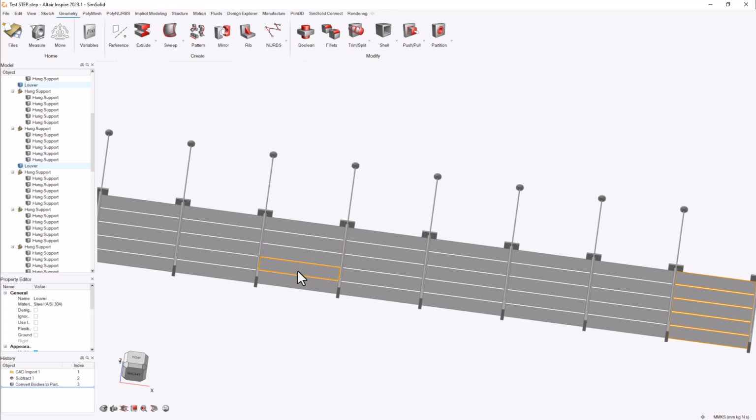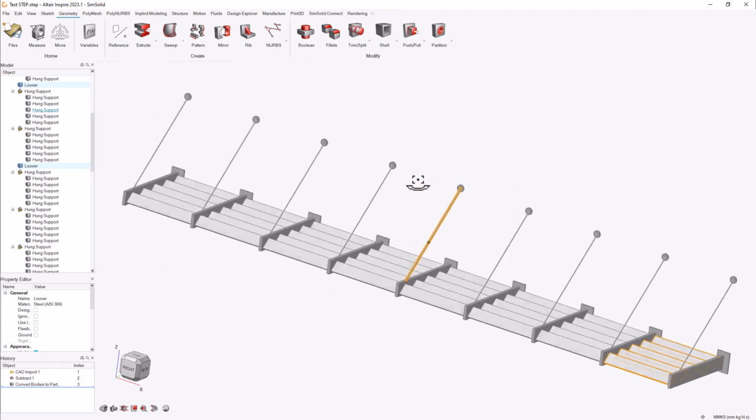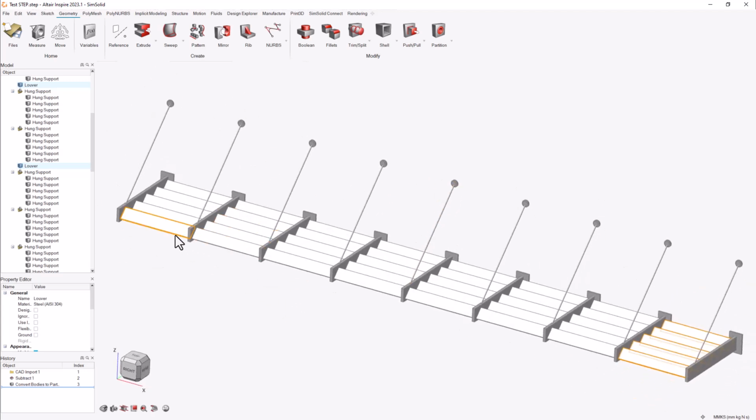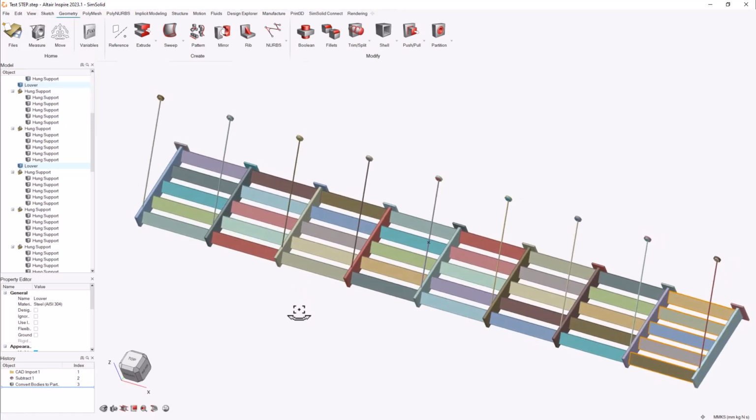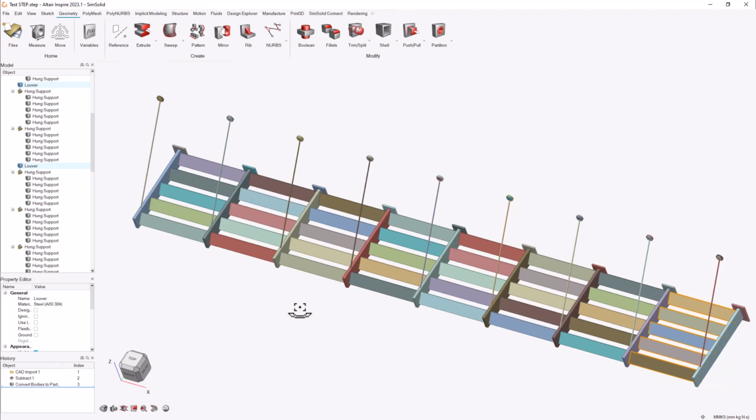And now they're all individual segments rather than one continuous segment that might be broken up or even not broken up like we saw before. We can actually display these with auto colors, so we can see these in different colors and just confirm again that they're not the same part. Now we can go ahead and run an analysis by applying our boundary conditions, our loads, our material properties and connections and so on. And I've already done that. I went ahead and did that already here.